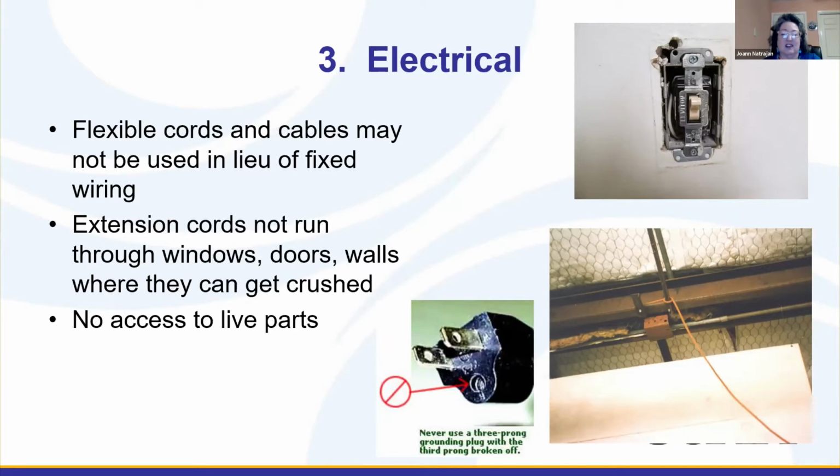Lastly, you can see that in many scenarios, if your equipment came with a grounded connection and the ground prong has fallen out, then that equipment no longer complies with what it's supposed to be doing. You've lost your worker protection. So we occasionally do see ground prongs missing.